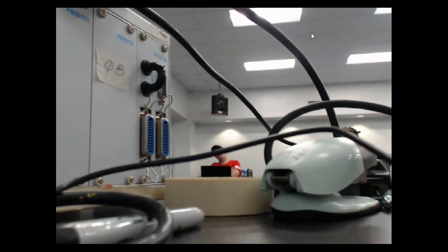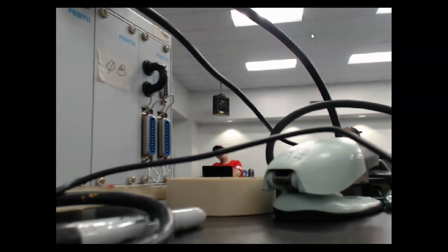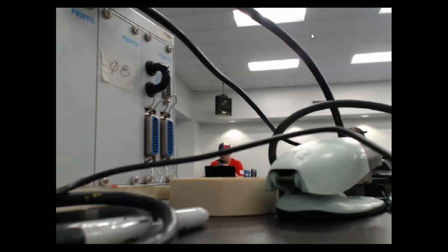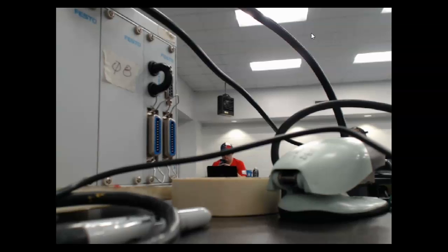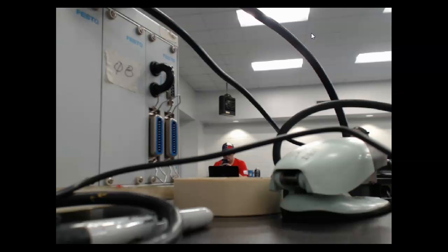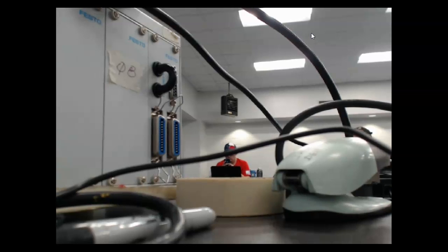So what would be the disadvantage of a relay output? First of all, it can't be as fast, because with relays, you have to generate a magnetic field. The magnetic field has to close the contact. So they're not as fast as solid state outputs. This guy here supports pulse width modulation, which is a method that we use to control DC motors. Even though this PLC supports it, I can't use it because the relays wouldn't switch fast enough.